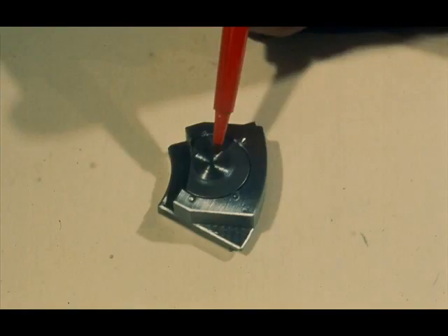On the reverse side of the shoes, a shoe support with a pivot button is permanently recessed in the shoe. The button is slightly convex to permit the shoe to rock in any direction to self-align with the shaft collar and permit the formation of the wedge-shaped oil film.